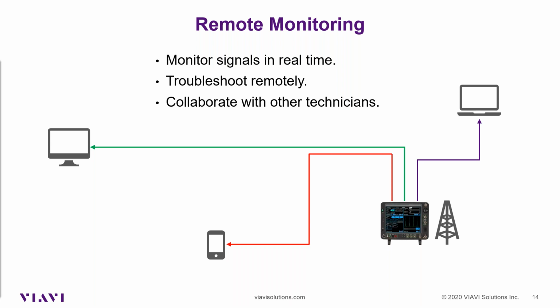There's nothing like going out to a site, not knowing what the problem is, knowing only what was reported. We get there, the problem's gone, it's working fine now. So what do we do? We shotgun a bunch of different components. We swap out radios, we swap out combiners, we swap out duplexers. And in the end, we hope that one of those things was the problem. We hope that we replaced whatever was faulty.